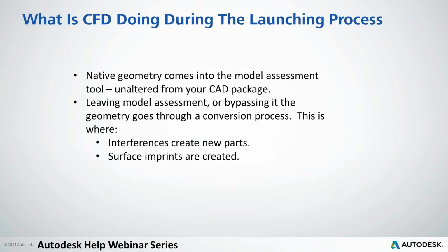I also wanted to talk a little bit about what happens during the launching process. What the model assessment tool is looking at is your unaltered CAD geometry from your CAD package. It's not doing the full conversion that we normally do when you come into CFD. Normally when you jump into CFD, shared surfaces are created as one surface. Your interfering parts will create new parts for the interference, and those surface imprints that we were talking about earlier are all created. So you'll see a couple of things.